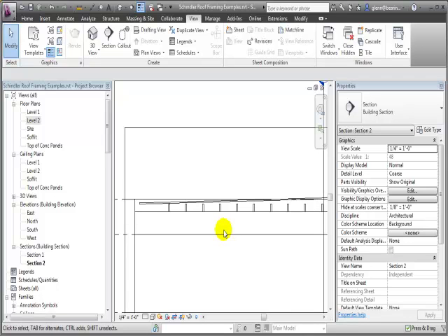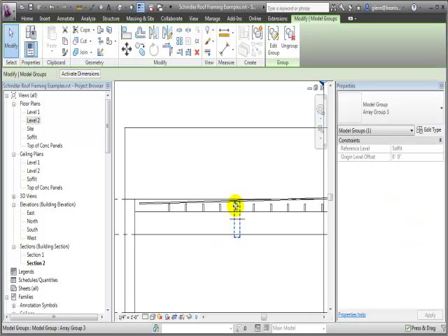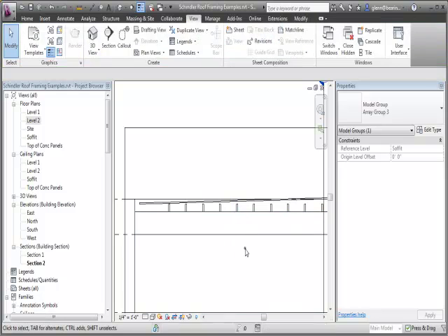Now, putting those all in as individual structure elements is really kind of a difficult thing to do. So let me suggest a workaround that may be a better way to model this that really has the same effect. One of the really nice features about walls is walls have the ability to go through and attach themselves to the roof above.